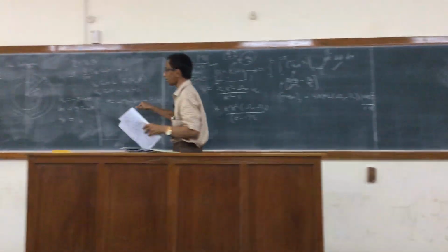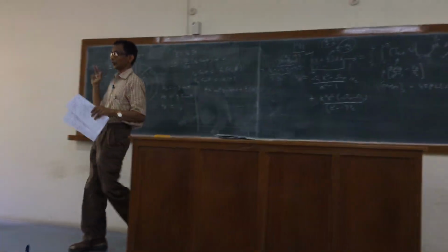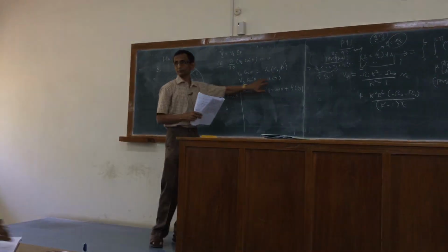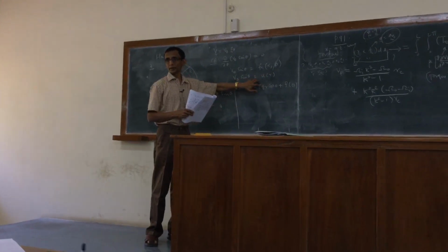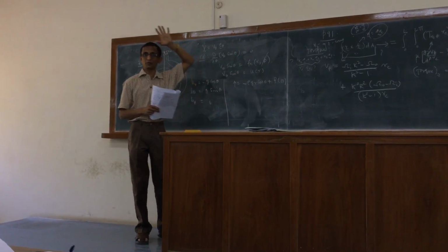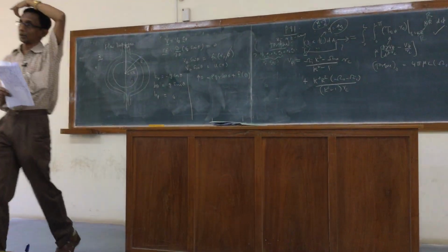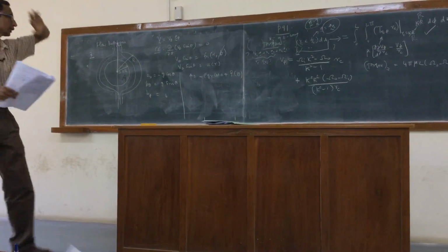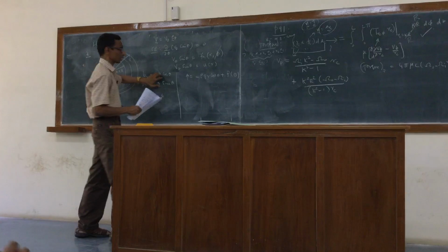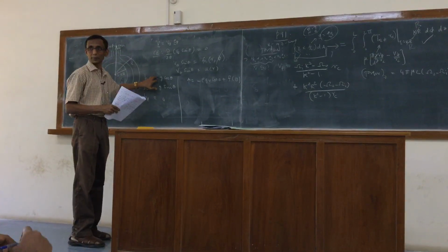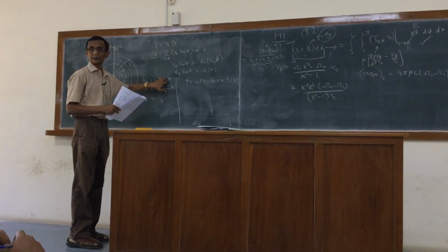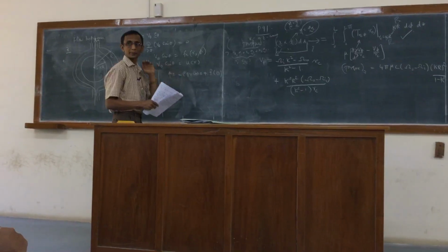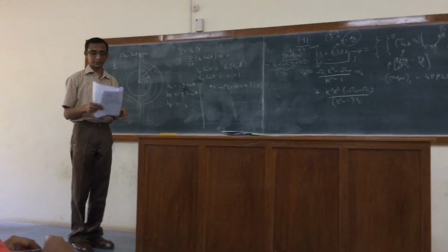We integrate the r component of the equation of motion, and you will get this. Once you have verified from the phi component that dp by d phi is actually 0, you can easily verify that this is just coming out of the integration of this. You get dp by dr, and you integrate this, you get rho g r cos theta. That's very easy to verify.